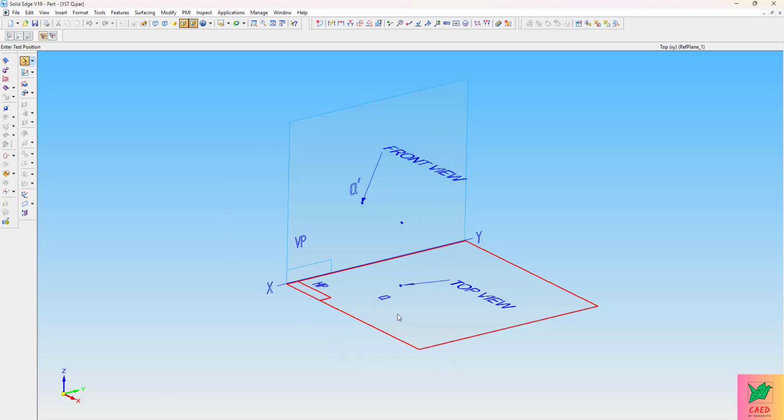See, here you can see this is the vertical plane. This is the XY line, right? Above the XY line, I have the vertical plane. And why did I consider HP below the XY line? Because I am tilting HP 90 degrees clockwise, so both are now parallel to each other, instead of perpendicular. The XY line differentiates VP and HP. HP is below the XY line and VP is above the XY line.